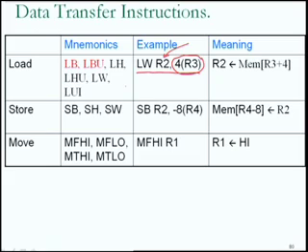So what this instruction means is, as indicated in the meaning column, the address of the operand has to be calculated as the sum of the contents of R3 plus the constant 4. So once this calculation has been done, that particular word of memory can be read, and that will be the new value of the register R2, the destination register. So the contents of the memory address as specified by 4(R3) are copied into register R2, and that's the meaning of the instruction.